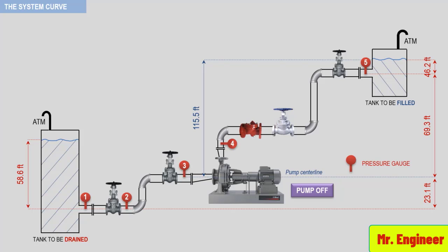Expel all air bubbles in the piping. Some pumps have a little petcock valve to allow expelling any trapped air in the volute. On the pump, conventional stuffing boxes can also trap air. This must be expelled too. Vertical valve stems in the piping can trap air, so loosen the packing to expel this trapped air. This is done so that there is a complete column of liquid from the top to the bottom of the system. Air pockets and bubbles might cause inaccurate pressure gauge readings.